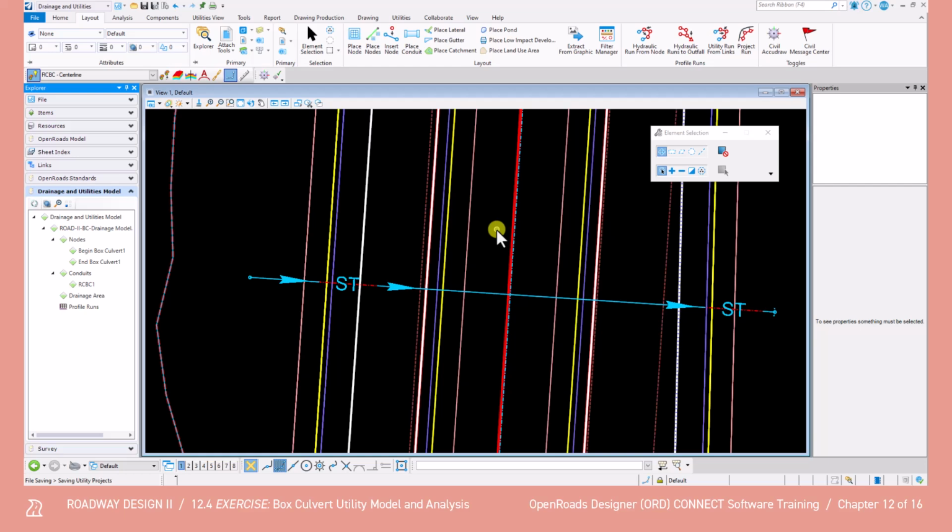Also, we meet the 500 cubic feet per second constraint, so we would not need to send this culvert to TDOT hydraulics. It is recommended to compare the area obtained from USGS to the area provided by the TDOT survey to ensure that they are not vastly different. We see in the image in the manual on step 17 that the highlighted area represents the area contributing to the culvert location. Notice that the drainage area boundary closely matches the boundary obtained from the USGS StreamStats shown in step 15.